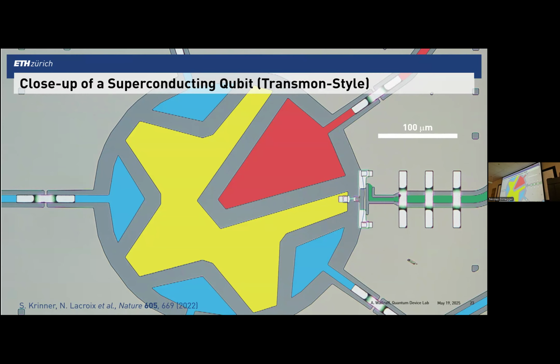You don't see the top of the chip because it is square. So it's essentially in 4 quadrants that the qubits get read out. And here the readout lines are not distinguishing between data and auxiliary qubits for quantum error correction, but they read out the set of qubits that is in proximity to this readout line. For example, I think Google, at least in some of the devices, made a different choice. So they had readout lines passing by auxiliary qubits and by data qubits separately. Good. Final question, and then I should move on so that I say something about error correction.